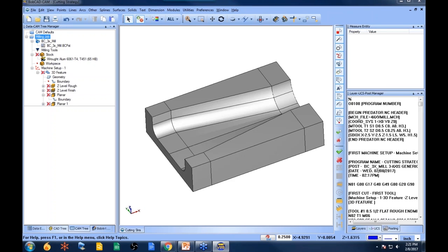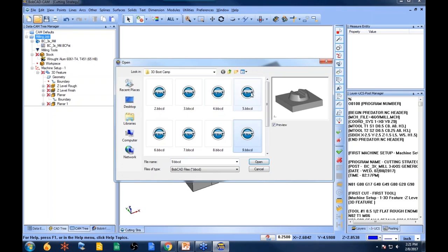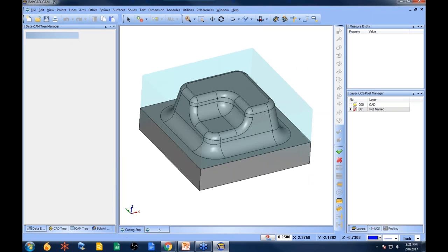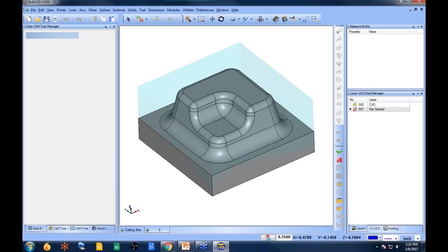Let's see here. Steve's got something. Can you turn over to the examples with many radius section? I often want to machine only one section, which does not end in a straight Z level. Angle, range, and boundaries. Yeah, Steve, I think what you're talking about is, let's see, this file here, and you had some questions about how you can target single surfaces or how you can keep the toolpath in one area. Today's agenda is really mill standard strategy, so you're kind of limited.